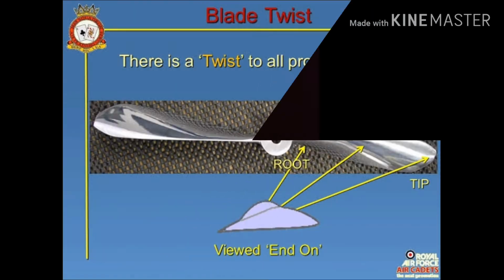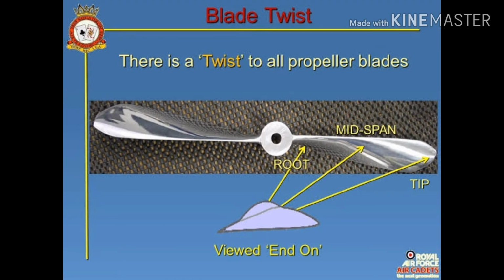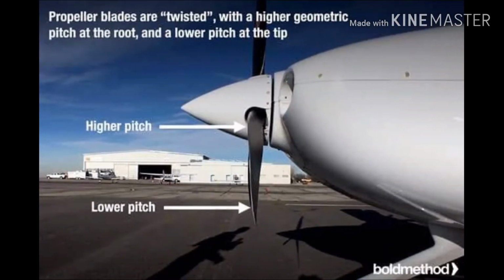Why is a propeller blade twisted? As a blade spins, its tip slices through the air faster than the part near its hub. The rotary motion combined with the airplane's forward motion changes the effective direction of the oncoming air at different points along the propeller blade.